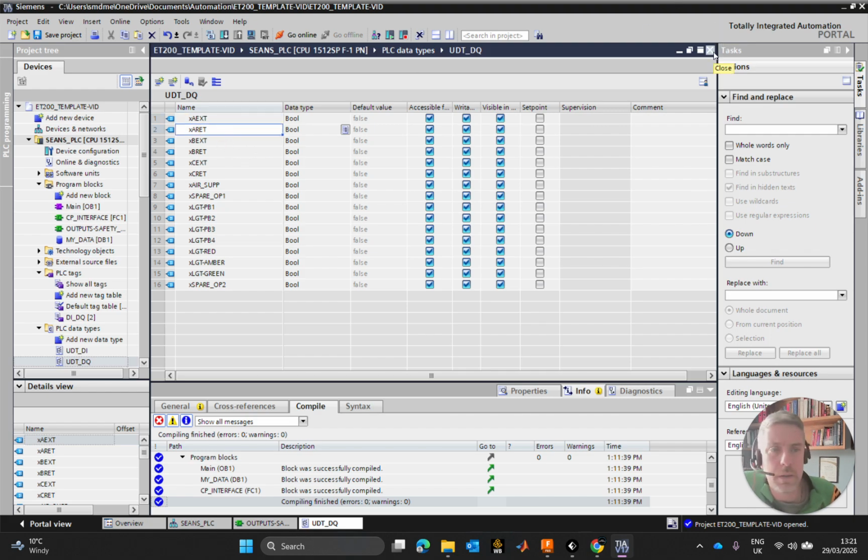You leave it there, because as soon as you take it out, you've created an inconsistency. The idea here is that if you're training a team, or if you are a team watching this, typically one person is going to be coding and one person is going to be building, but you both need to know the order of how you plug into each of your inputs and outputs, and you need to know how they're coded. You need to know that this is A extend, A retract, B extend, B retract. B extend is always in percentage sign Q 0.2, always.